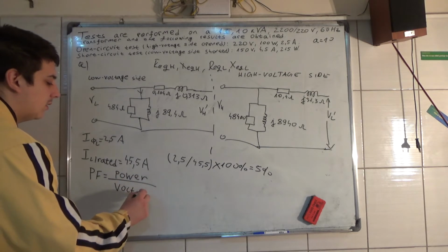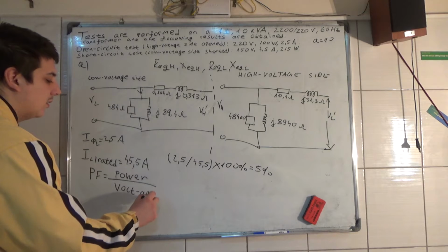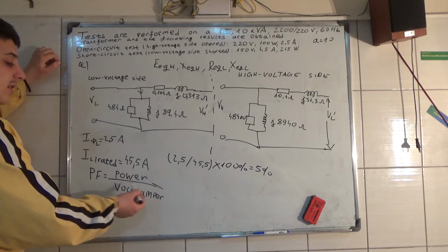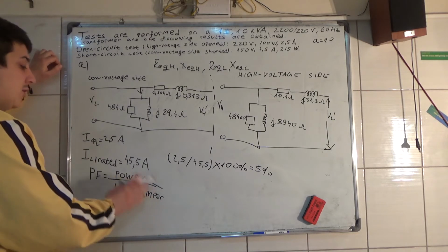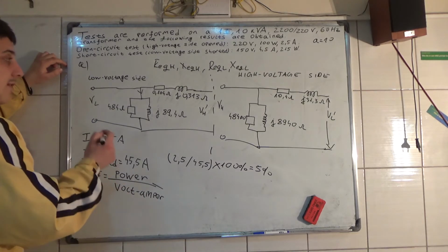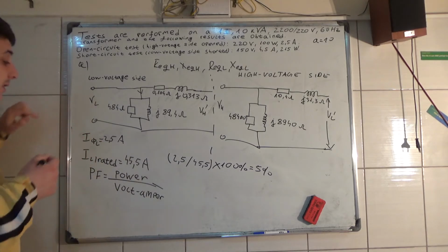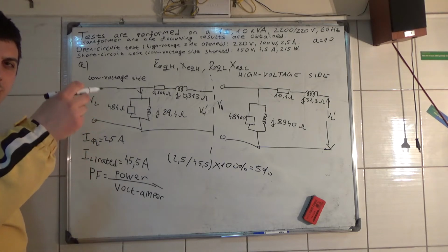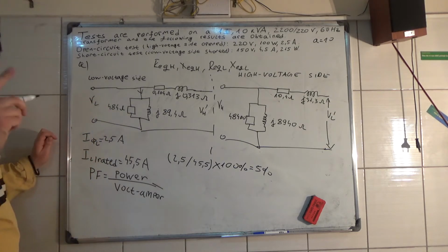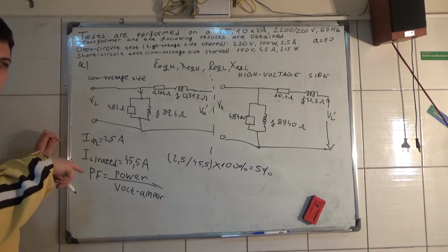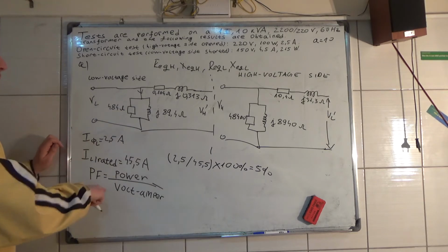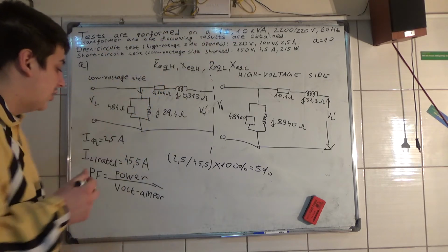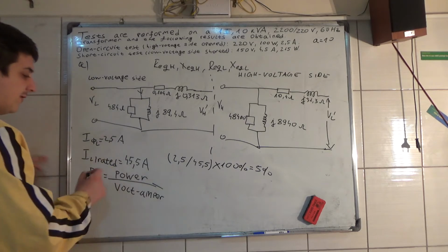So when you divide the active power by the apparent power, the full power, you get the power factor of the circuit. That is the cos phi, if you remember it. And we don't put the number 3 here because it's a one-phase circuit. It's not three-phase.